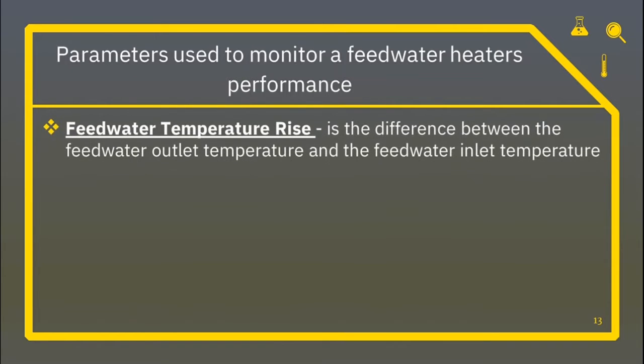First is the feedwater temperature rise. It is the difference between the feedwater outlet temperature and the feedwater inlet temperature. A properly performing heater should meet the manufacturer's design specifications, provided the level controls are up to the task.